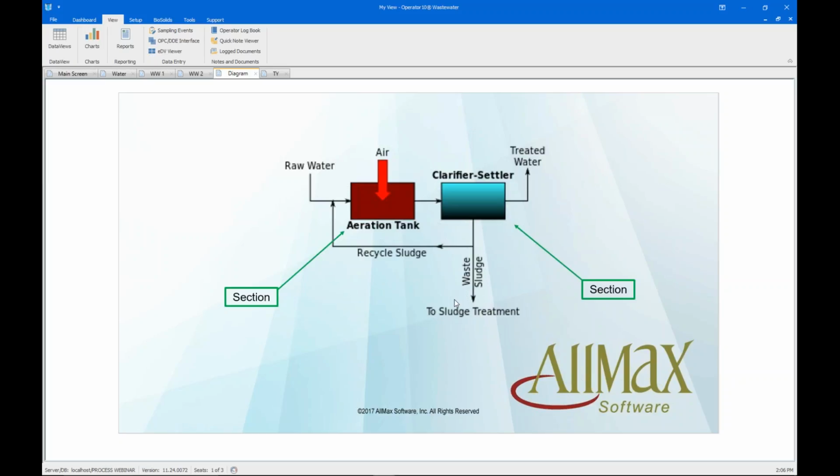In your aeration tanks, you may have to have an F/M ratio or an MCRT of a certain value to make sure it's running as optimally as it can. That varies from plant to plant, but the idea is what information you're going to need. Operator 10 can generate all that information based on the criteria that you designed for it.